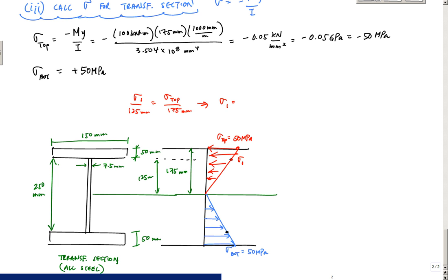That's going to be some number, which is 36 megapascals right there. Okay, so 36 megapascals, and that's the same thing down here. This other point right here is also 36 megapascals, right where I transition from the flange to the quote-unquote web, which is wood transformed into steel. To draw the strain profile, I just had to divide every single number here by the modulus of elasticity of steel.